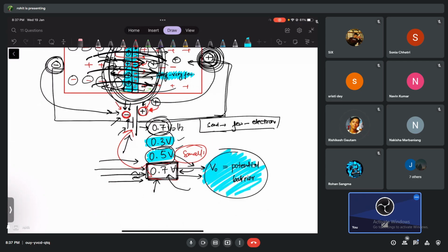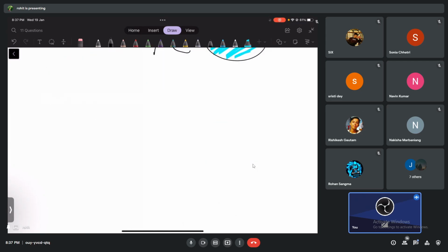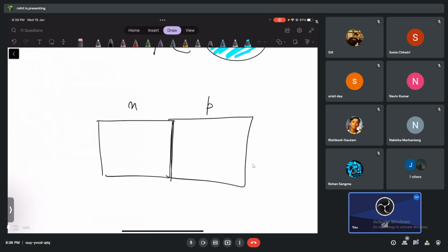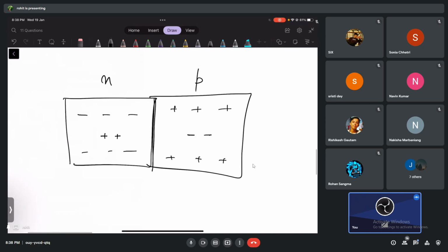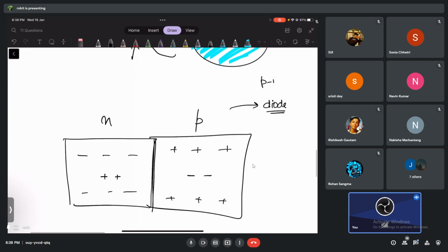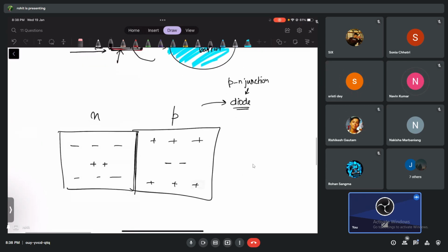Yes, sir. Okay, so I'm going to ask you a very quick question. What did you learn just now? If I take an n type and join it with a p type, n-type has majority negative charges, electrons. P-type has majority holes. We also have minority charges: in n-type the minority are holes, and in p-type the minority are electrons. What is the first thing I told you happens, guys? The moment we join them, we get a device which is called a diode. Its full name is PN junction diode. PN diode also you can call it, but let's say PN junction diode.